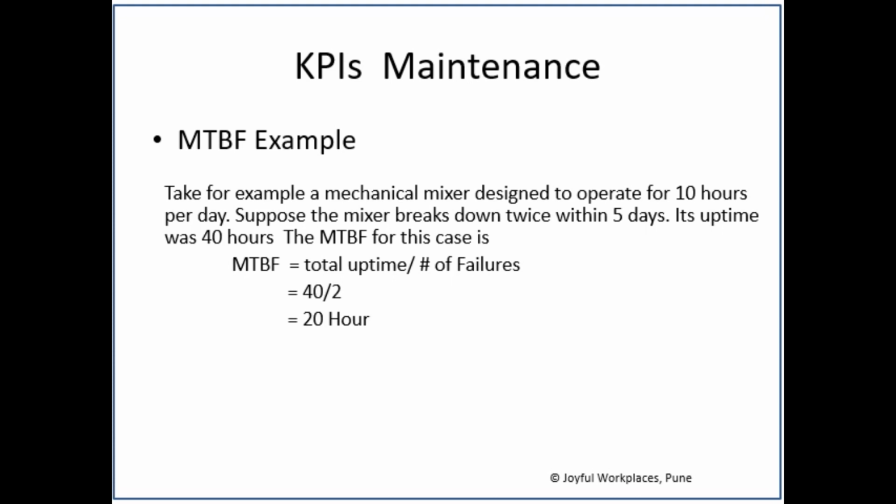So what is MTBF showing us? It is showing us the time lapse between the failures. So if I ask you what should be the ideal value of MTBF, the answer is that it should be as large as possible, unlike MTTR, which was as low as possible. MTBF should be as high as possible because it shows me the distance between two failures.